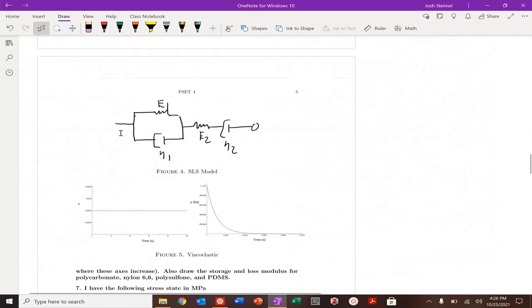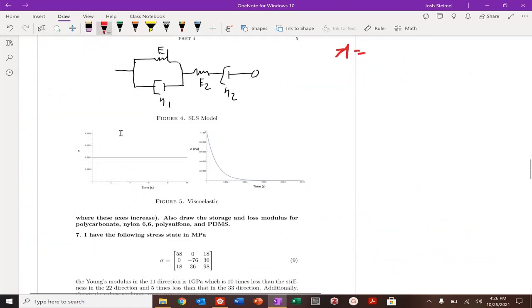So let's do the same for this next one. Remember, at time t equals 0, once this is stuck, this won't move, this won't strain. It's basically infinite stress. There's no strain in this component, but I'm going to have the strain here, so it'll look kind of like E2 again, but you're going to be constrained here with this immovable box. At time t equals infinity, this is disconnected. So you're basically going to pull nothing, because we're disconnected there. So there's no stiffness.